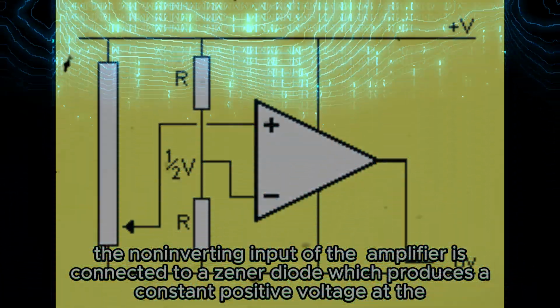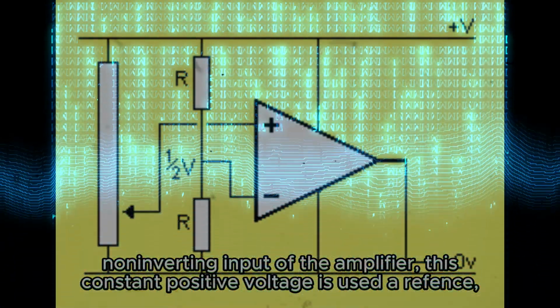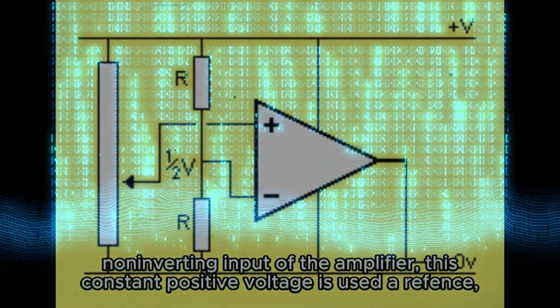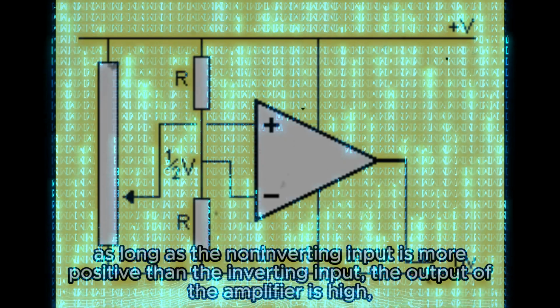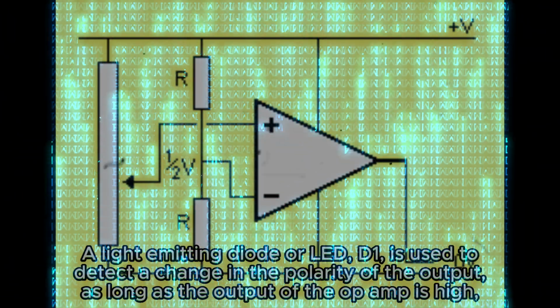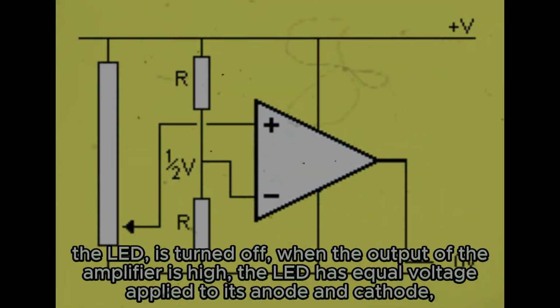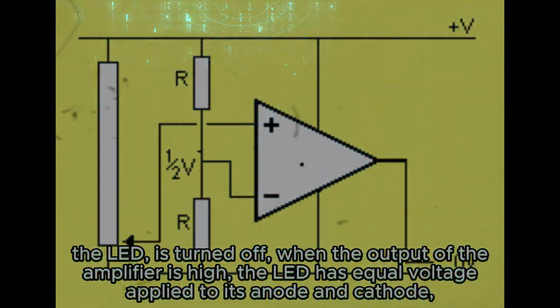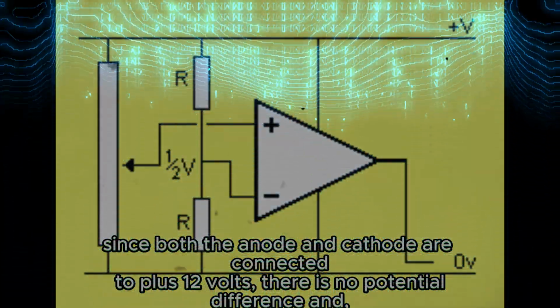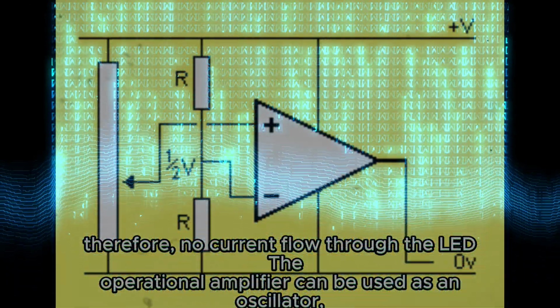The non-inverting input of the amplifier is connected to a Zener diode, which produces a constant positive voltage at the non-inverting input of the amplifier. This constant positive voltage is used as a reference. As long as the non-inverting input is more positive than the inverting input, the output of the amplifier is high. A light-emitting diode, or LED, D1, is used to detect a change in the polarity of the output. As long as the output of the op-amp is high, the LED is turned off. When the output of the amplifier is high, the LED has equal voltage applied to its anode and cathode. Since both the anode and cathode are connected to plus 12 volts, there is no potential difference and, therefore, no current flow through the LED.